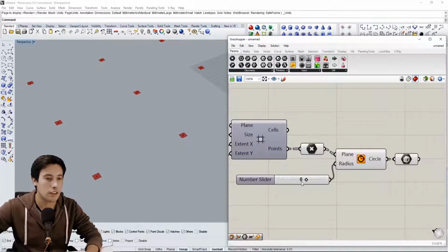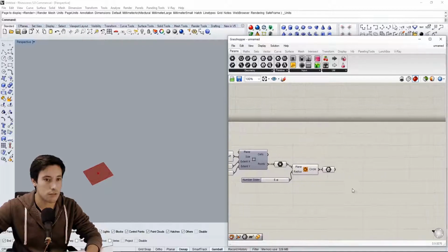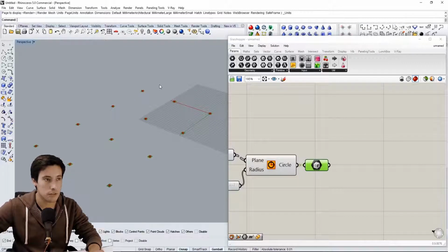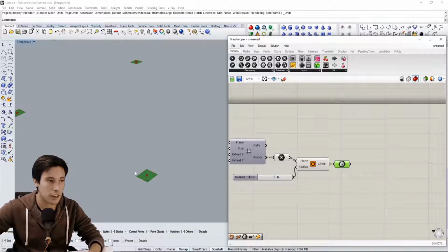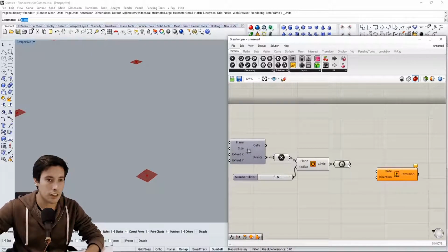So now we have a 6 inch from the center point to the outside and 6 inch. So that gives us a 12-inch square base that we're now going to extrude to give us the array of columns. So now we can move on and extrude these boxes that we created. So there are actually planes here that are created around. So let's extrude it. Double click, extrude, and we'll plug in these boxes and we're going to extrude them up.